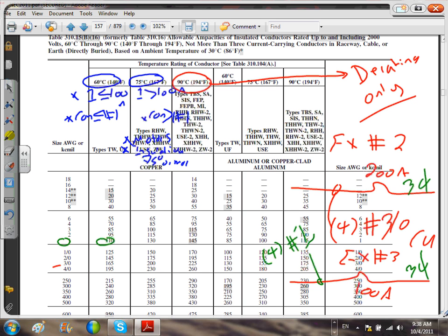No matter what, the small conductor rule says number 14, number 12, and number 10 cannot carry more than the following; you cannot land them on a circuit breaker rated more than the following. So please highlight this, and these I already highlighted by the code for you guys, these two. These are the small conductor rule. What does that mean? No matter what, you can't make a 14 carry more than 15 amps. You can't land it on a circuit breaker more than 15 amps.